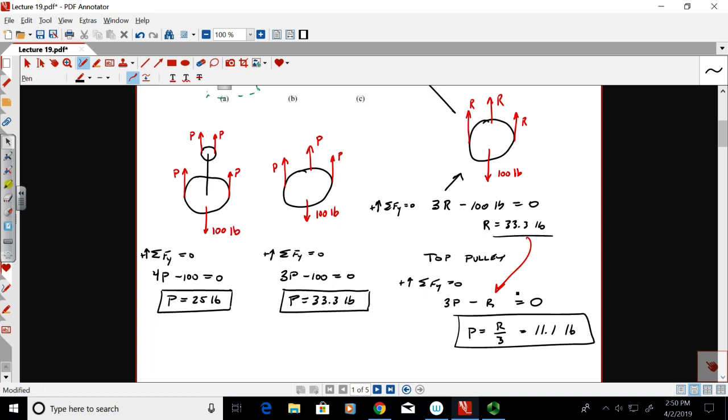Okay, well, if you want to lift the front end of the car 10 inches, you're going to have to use 90 inches of rope pulling down in order to do that, right? Because even though you get a multiplication of 9 on the force, for every 10 inches that the end goes up, you have to pull down 90 inches of rope, okay?